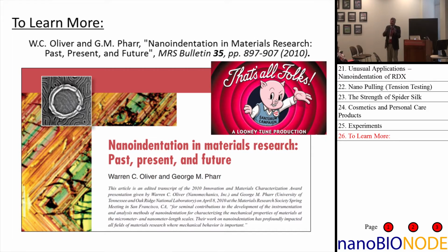We do it all inside of a dual beam FIB, where the FIB becomes your eyes and your hands, because you've got nano manipulators in there to pick things up. The nanoindentation equipment is added inside there to measure the forces and displacements with the requisite resolution as you're doing the test.